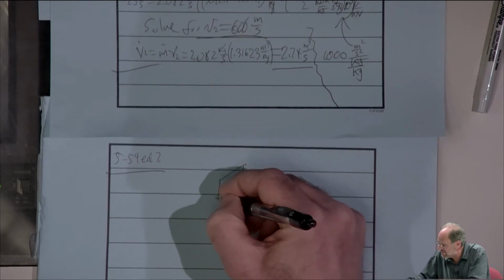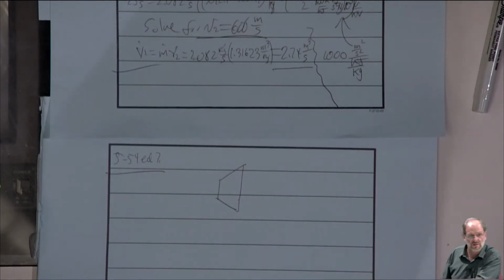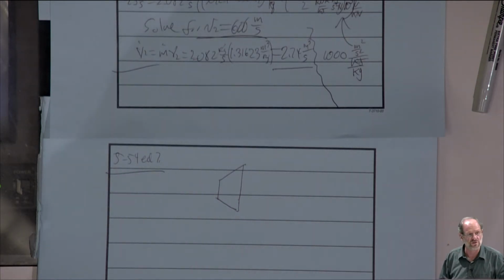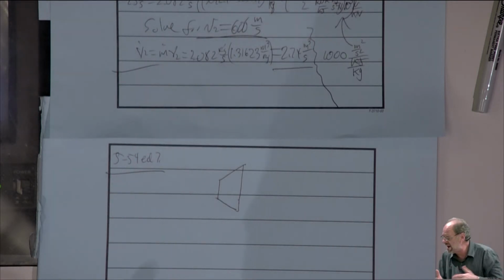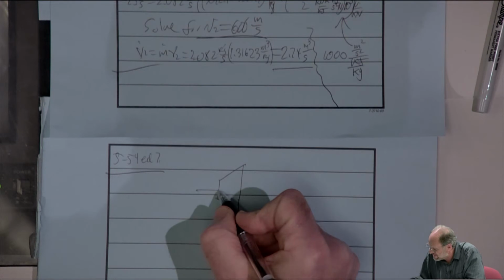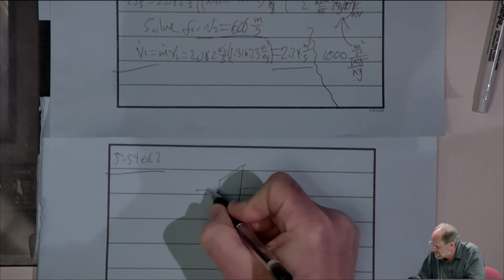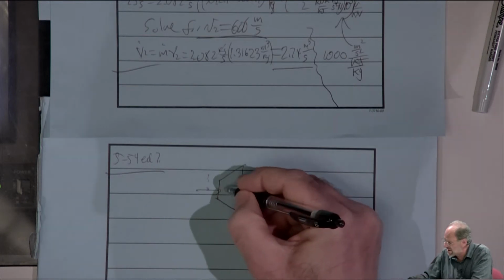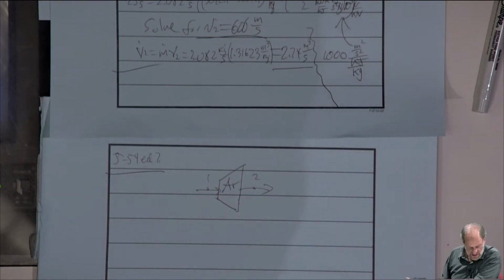We always show turbines as trapezoids. If you look at a turbine in cross section, they always get larger as the substance flows through the turbine. Its pressure is always going to drop. The specific volume is always going to rise. So in the real world, you need to have a casing that's increasing in size to accommodate that larger volume. So we always have an increasing volume for the turbine, and therefore we show these as trapezoids, increasing left to right. It's argon gas, so it's got argon inside.